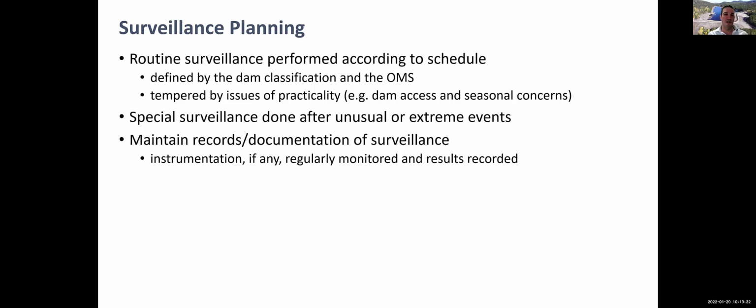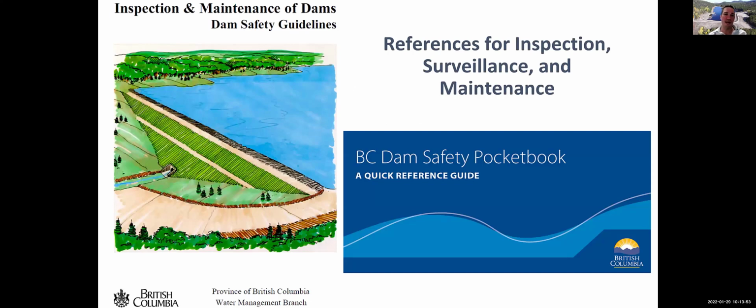You will want to increase surveillance, or have some post-seismic surveillance. Or after an atmospheric river. Yes, or after one of those. Or maybe during, or before, if you know it's coming, you go up there and make sure your spillway doesn't have a beaver dam in it. Exactly, be proactive. Right, and make notes of it. So we just keep hammering that home.